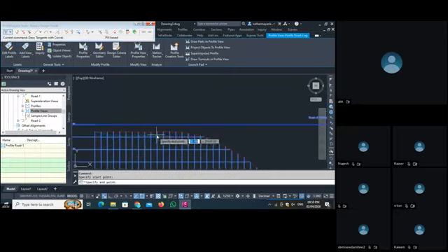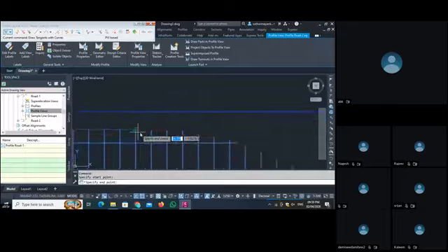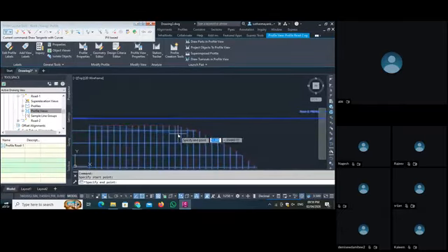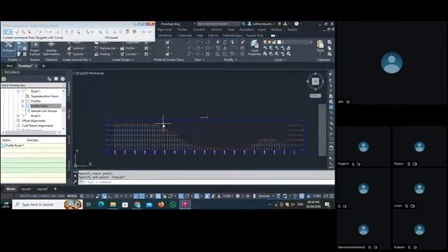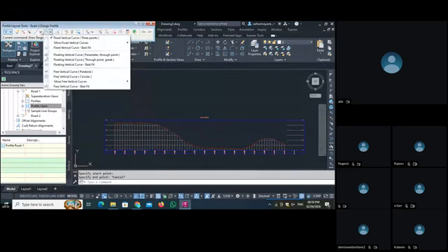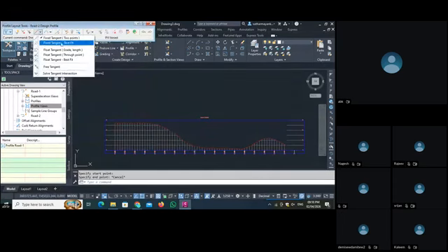See, make sure you select your profile, as there is no more cut and no more fill. You can select your design profile with the help of these tools. See, fix the tangent based fit. You can use this tool also.